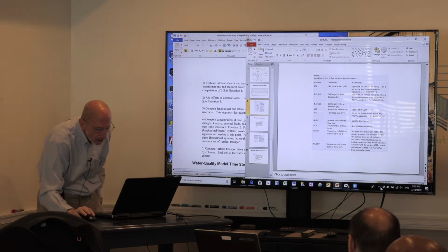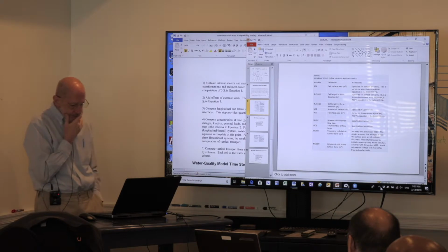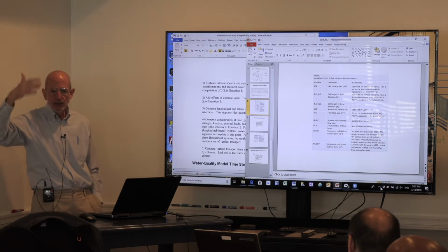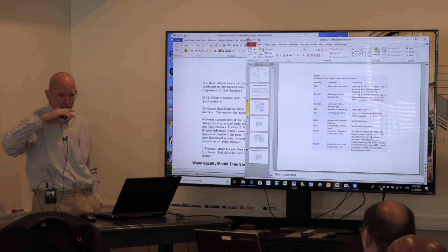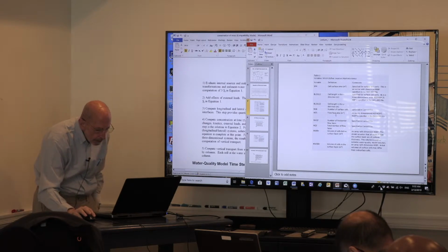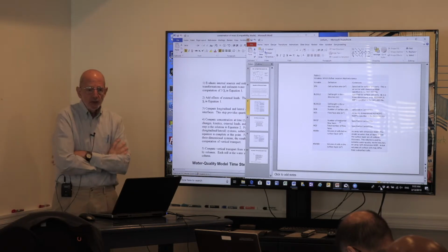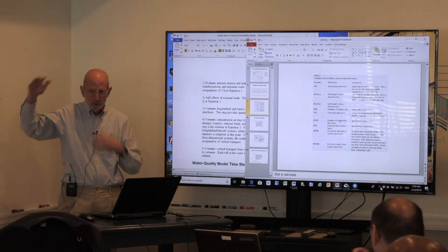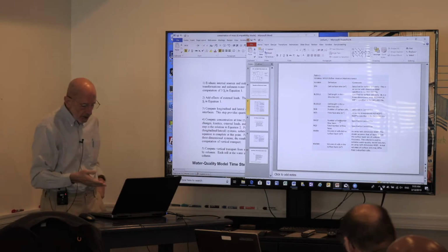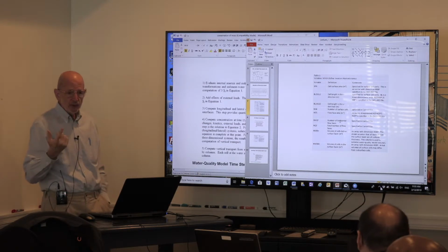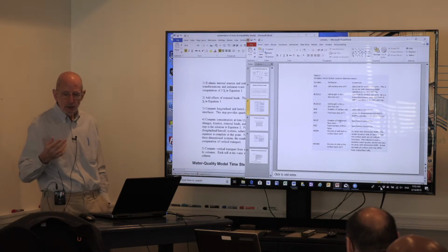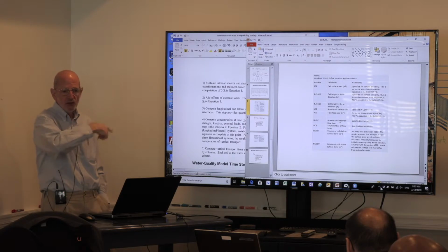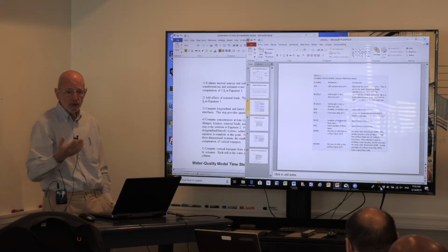The flow face area. That's the cross-sectional area of a cell, if you will. We're going to talk about this in detail. The number of horizontal flow faces. We have flow faces in the horizontal directions. We have flow faces in the vertical. So the number of horizontal flow faces is something you specify once. It's an index. When we go to solve the conservation of mass equation, you're going to go from 1 to the number of faces. So that's something you have to provide.